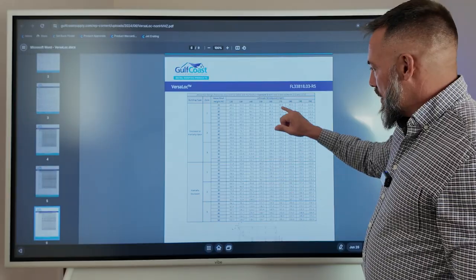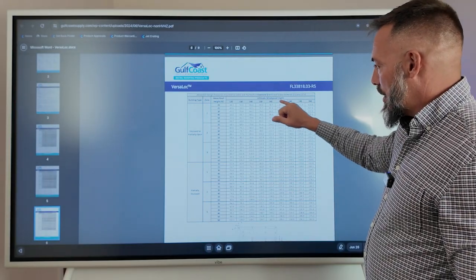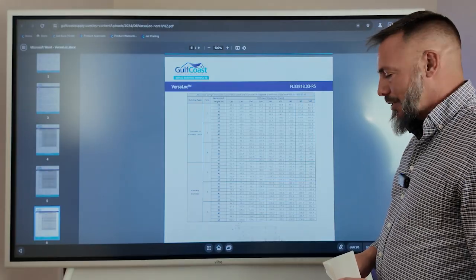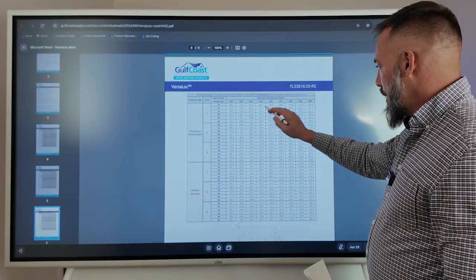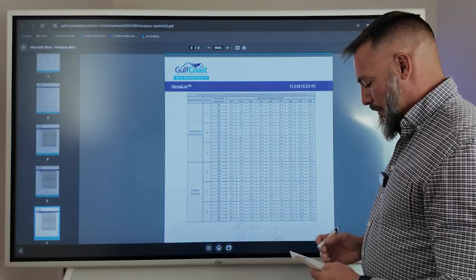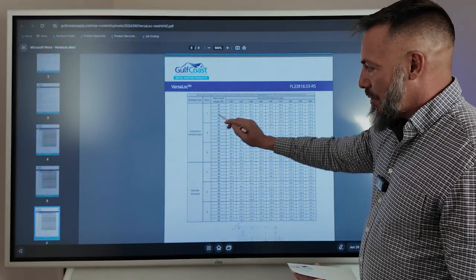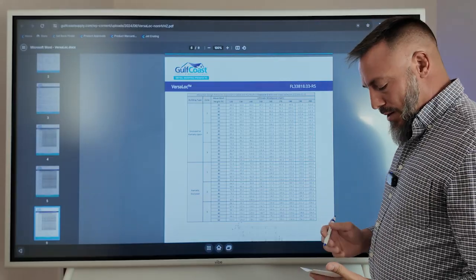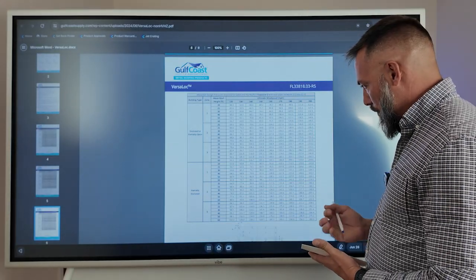But for the video, what I'm gonna do is bump up to the next highest wind speed, and then I'm gonna go with the highest wind pressure just to kind of show you what pressures we need. So we were at 164, we'll bump up to 170, 60-foot roof height. You need 3 pressures. You need a zone 1 pressure, a zone 2 pressure, and a zone 3 pressure. I'll go over that more in a minute.